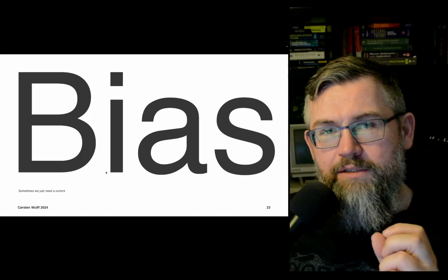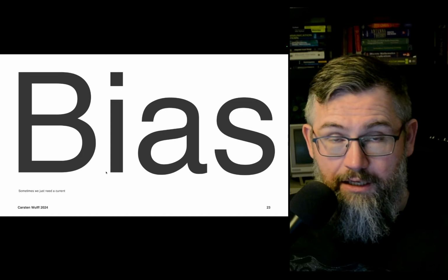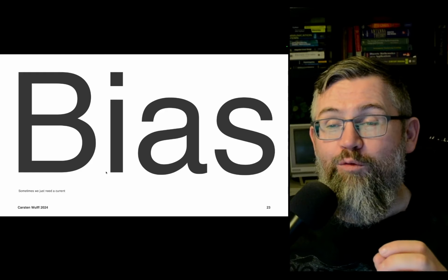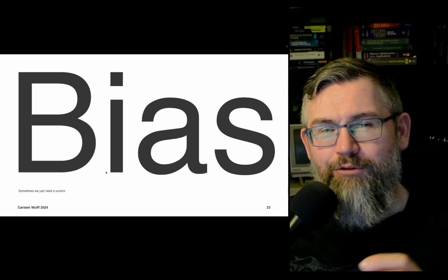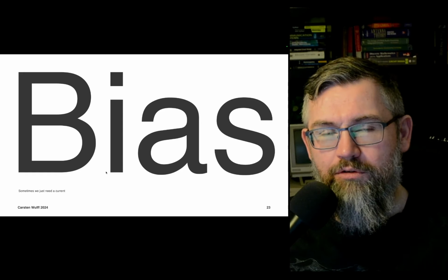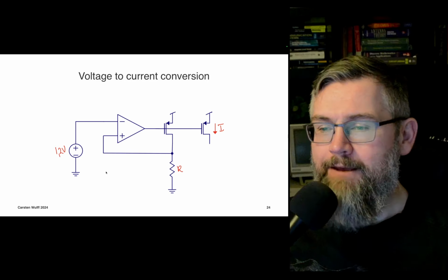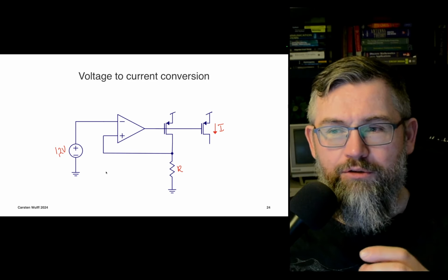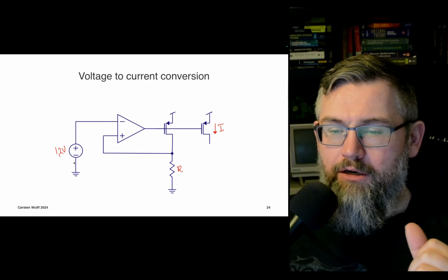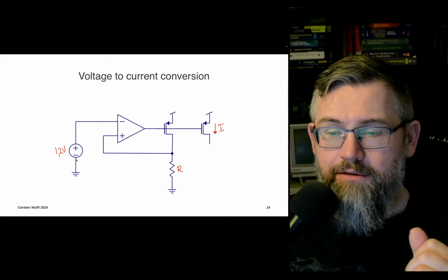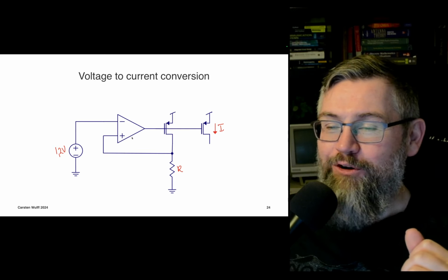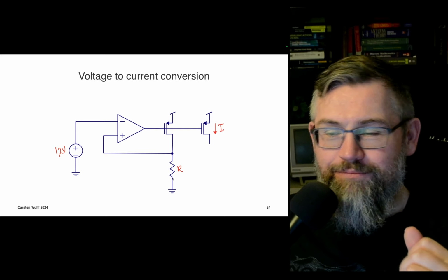It's not always that we need voltages, as I said in the beginning. Once we have a fixed voltage, which we now have, we quite often want to generate a current instead to be able to reliably distribute all across the chip. One way to do that is to use a voltage current converter. And what we're doing now is we're taking our fixed point in voltage, at the 1.2 volts, and we're copying that voltage across the resistor.